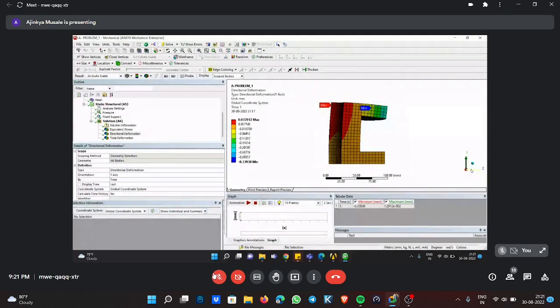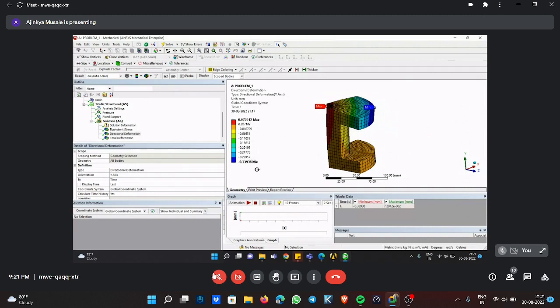Maybe I'm having y in upward direction, so whatever is in the upward direction is positive, and whatever comes below this axis, in the downward direction, is negative. If this tool is deforming in the negative direction, that's why it gives me a negative sign. But practically my deformation is always a positive digit. If you see the example here, 0.33 millimeters, it should not be negative, it is always a positive number, right?